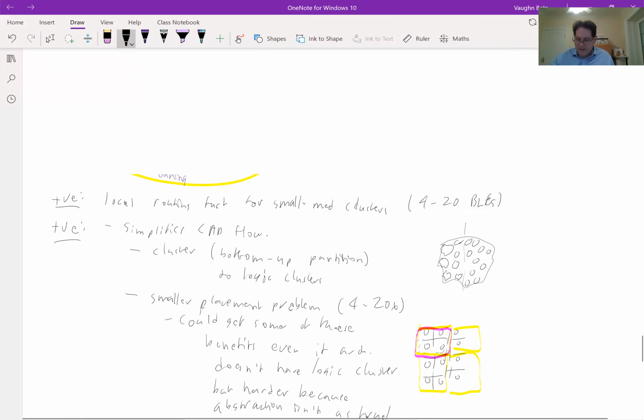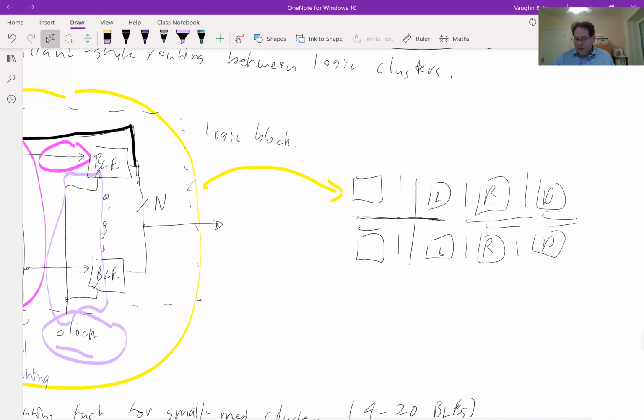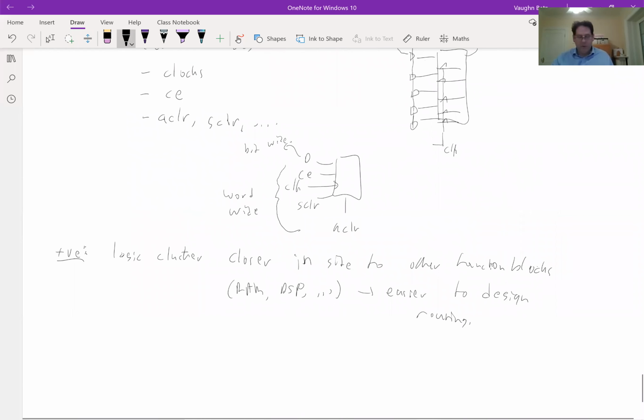So the design is not just the layout. This does simplify the layout, but the other thing, which you're going to see in the next part of this lecture, is that if we have some blocks with a lot of inputs and outputs, and other blocks with very few, they have different demands on the routing. That would make it very hard to choose a routing channel width and have it go through all the blocks evenly in the way I've shown here. So basically, if we have wildly different sizes of blocks, it is more difficult to design the programmable routing to satisfy them all, and more difficult to lay them out.